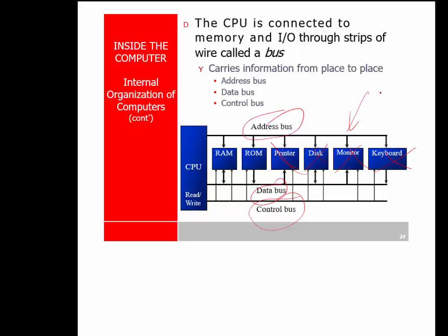The monitor is connected to either a D connector for VGA, a little square one for DVI, or now DisplayPort is out there. A lot of the video cards have HDMI output, so you have all kinds of graphics standards out there. This one has a DVI connector, and this connector is not very reliable. This one has a DisplayPort output, so I have to use an adapter, which seems to be giving me trouble getting a VGA out.